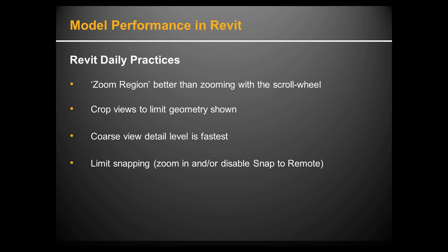So we do have quite a few things. Matthew makes a comment regarding family size. I've read that only the initial load contributes to the file size and repeated instances don't, but more instances will slow down the view refresh. That's true. The other thing that people do, Matthew, that, obviously you've read this, so you're working more efficiently, a lot of times what people do is they initially load the same family element a lot of times, and they don't instance it properly, and so there's where you get into trouble fast with families that you pull in from exterior sources.